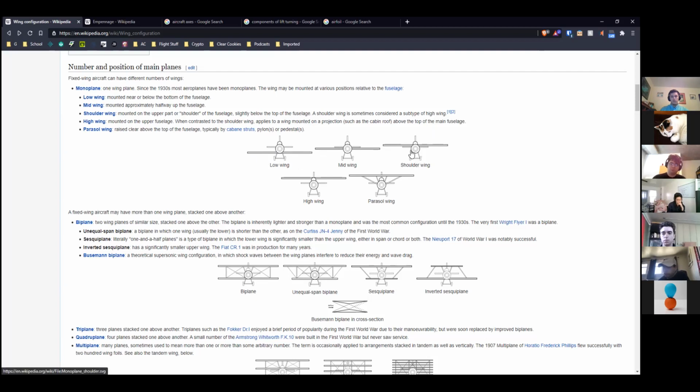But the other main thing this affects, in a manned plane would be visibility, but for us it's ground clearance. It has some minor performance impacts, because on a high wing the fuselage can mess with the flow more, since a lot of the important flow stuff happens behind the wing, than in a low wing, but it's not that different.